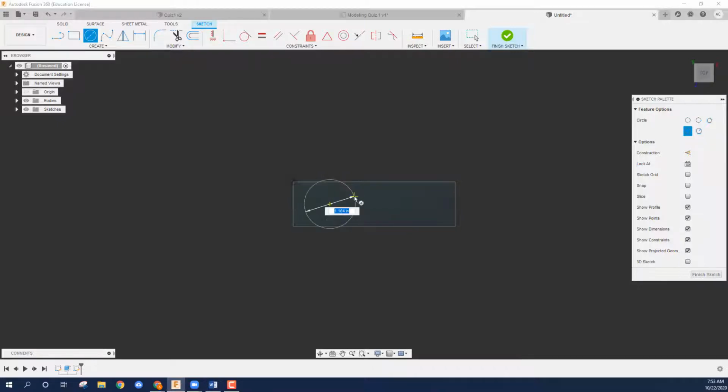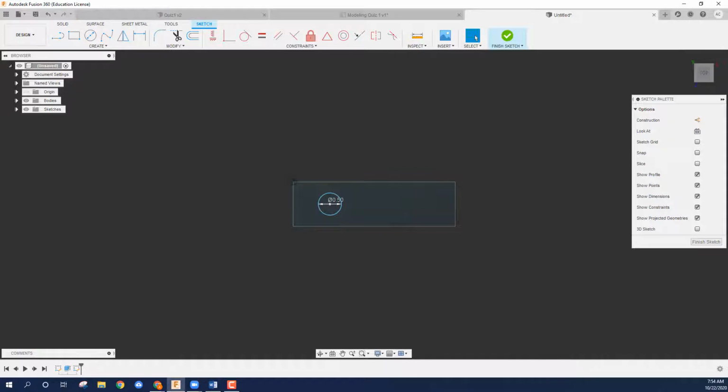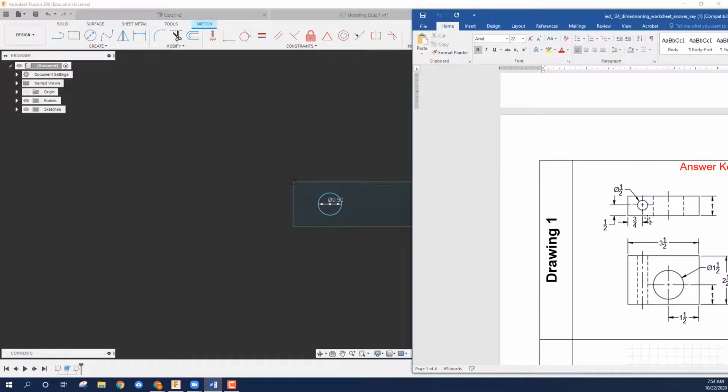Now, guys, something just happened that I wanted you to notice. If you see the green dotted line there that's running from the left-hand side, I just happened to put my mouse right in the middle of the distance between the bottom and the top of this object, and that green line is showing me, hey, you're right in the middle there. It's just happenstance. I actually know that that's where I want the center point, so I'm saving myself a little bit of work here. So when I look back at my sketch, I can see that the distance from the bottom edge of this surface to the center is a 1/2 inch, I've already set that up.